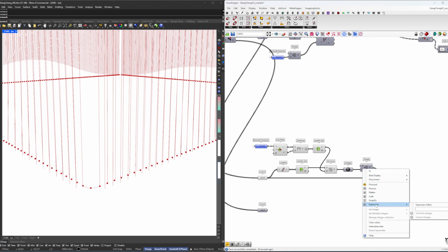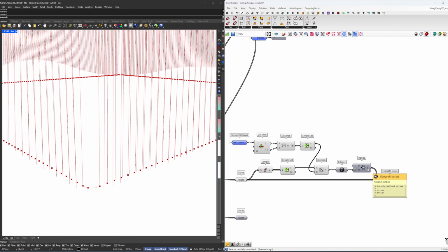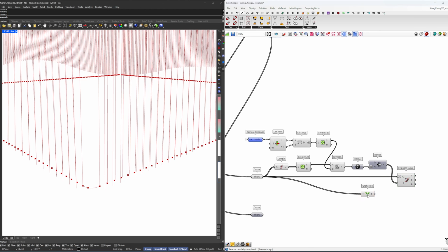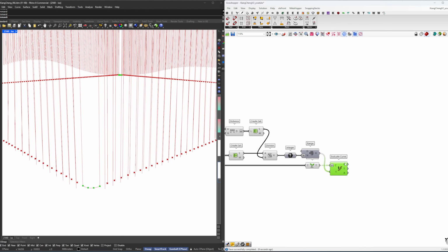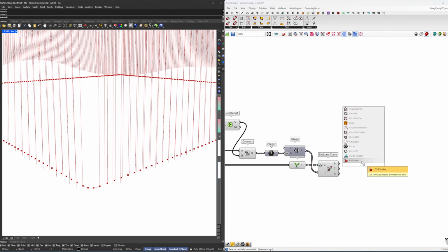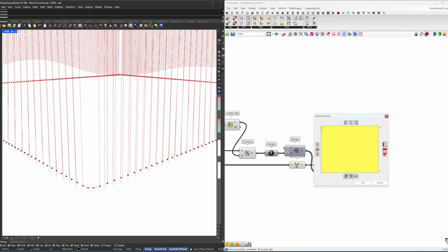So let's do a small trick. Let's just do x plus 1. And now we get 3 points, right? Oh wait, we need to graft. Never forget to graft your lines. So now we get 4 points here. And that's exactly what we want, because now we're going to cull the first curve and the last curve. If you use a -1, it's always going to be the last curve, because those curves we don't want to create. And you need to multi-line data this. So now we just have these 2 points here.